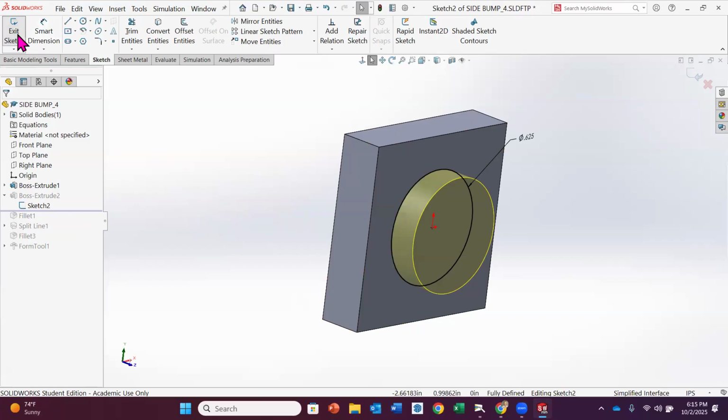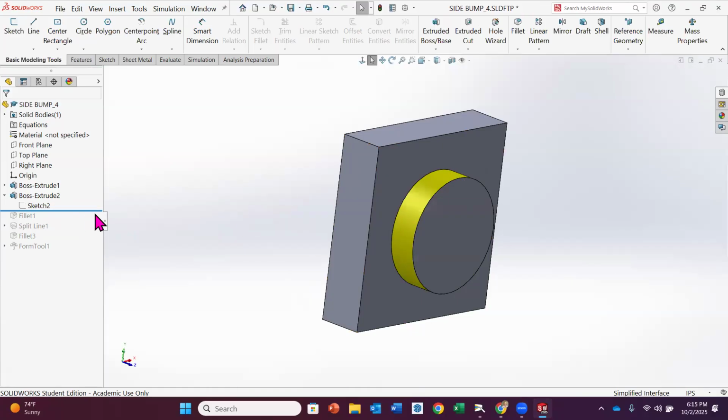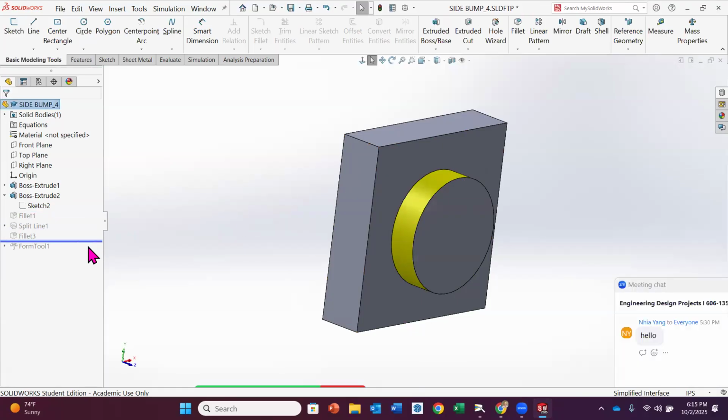And then once I got that in place, the next thing you just need to be aware of is you're going to be putting these radiuses on, because when you do sheet metal, you can't have real sharp corners. It's always going to have a bend in it. And when possible, you want to give it as generous a radius as you possibly can.